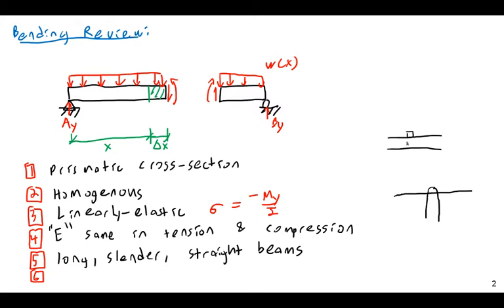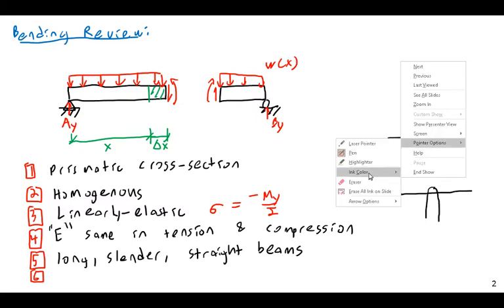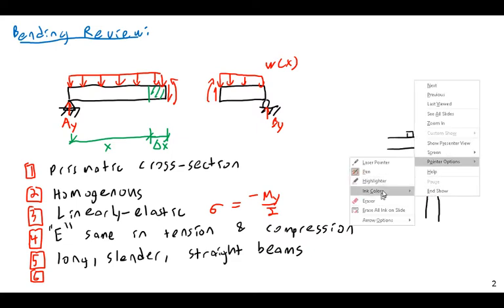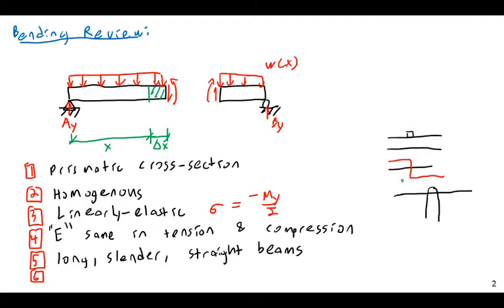So in our shear diagrams, we will say that the shear will just instantly drop at the location of that point load. But if you were to model it very accurately, it would look more like this, with a transition zone.